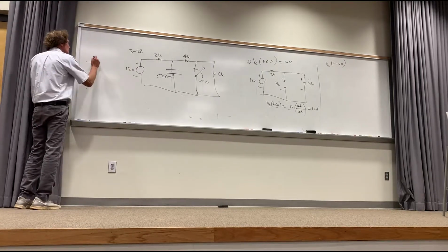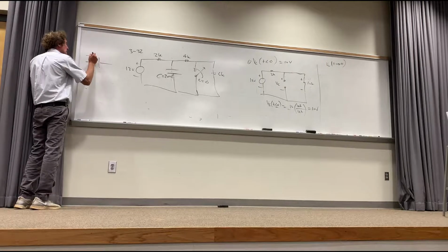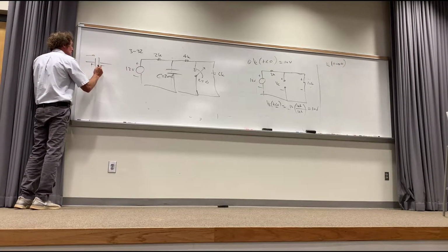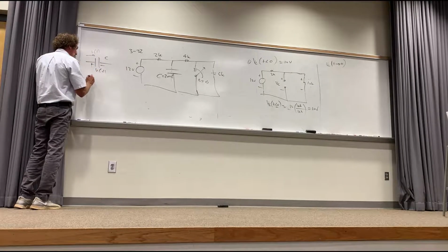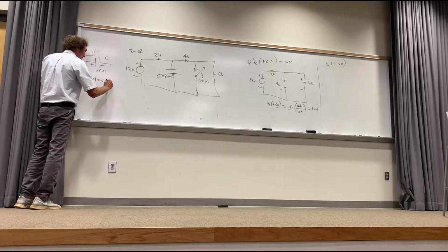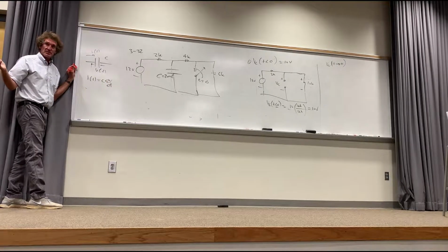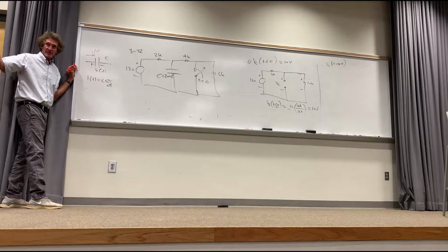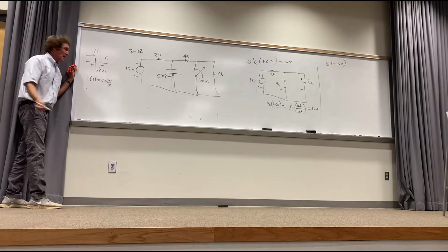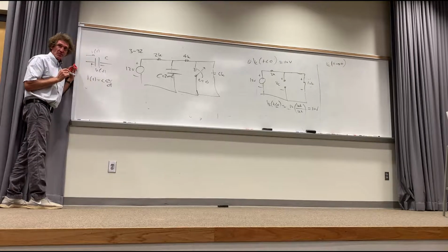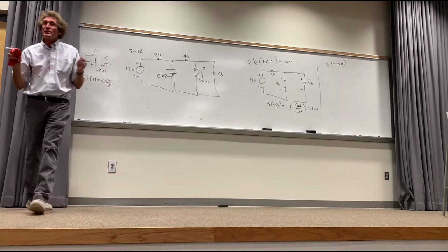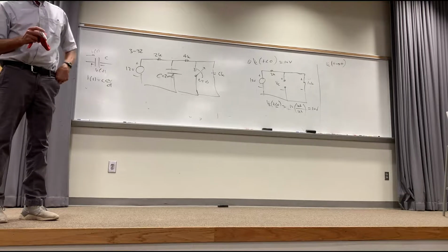Remember this always. You've had it in physics. If this is plus or minus the voltage across the capacitor, and this is the current through the capacitor, then I through there is C dV/dt, right? The definition. If nothing changes with time, go back to the beginning of anything, go back 1 billion years, nothing's happening. The rate of change of time of the voltage is 0. If the voltage change is 0, it means I equals 0, right? If I is equal to 0, it's an open circuit. You can replace it.